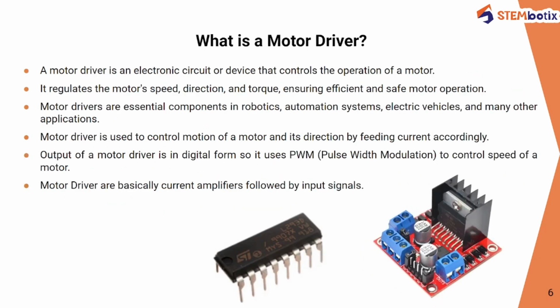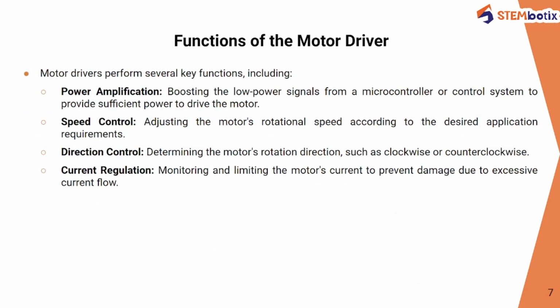So after seeing motor and motor driver, let us see the functions of these motor drivers. So why are the motor drivers there? Motor drivers perform several key functions, including first, power amplification, means boosting the low power signals from a microcontroller or control system to provide sufficient power to drive the motor. Second is speed control, means adjusting the motor's rotational speed according to the requirements of our application.